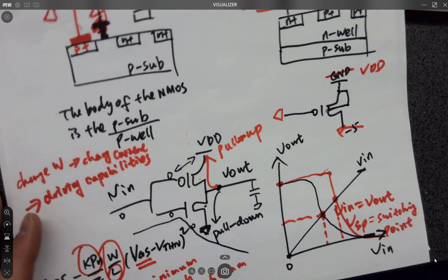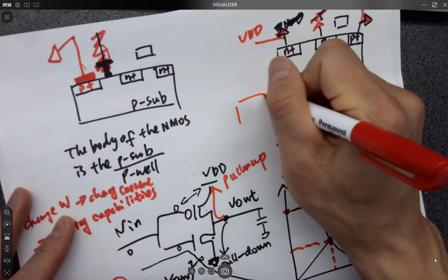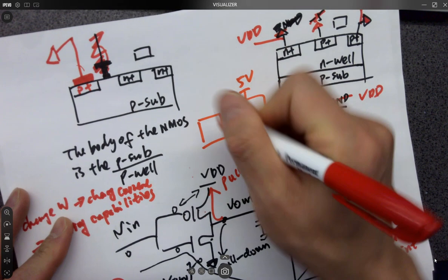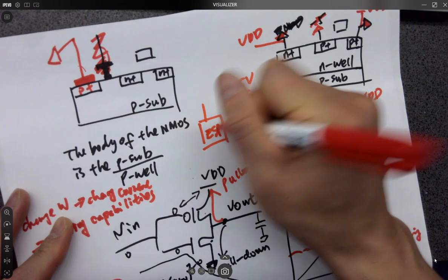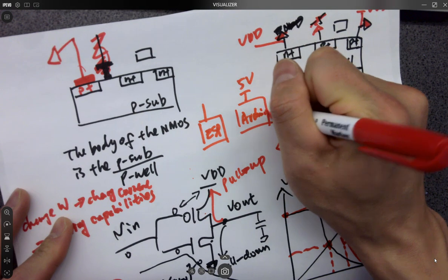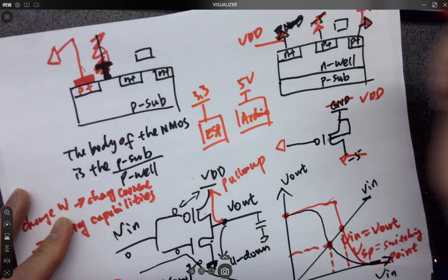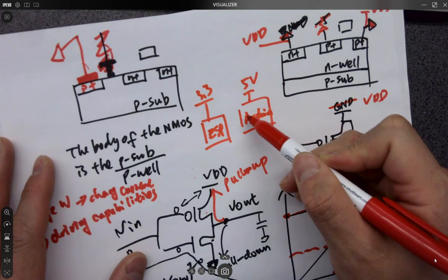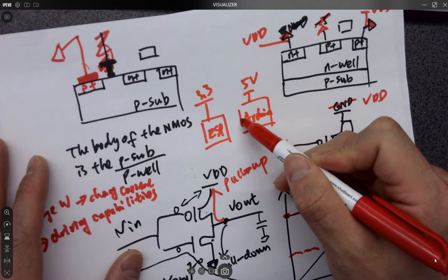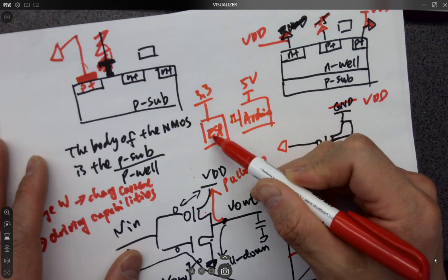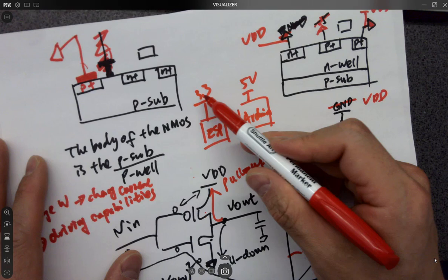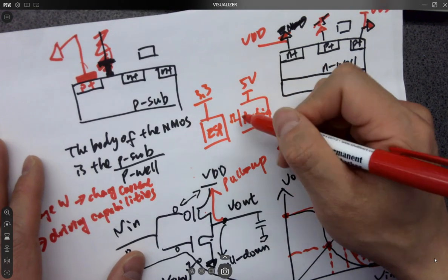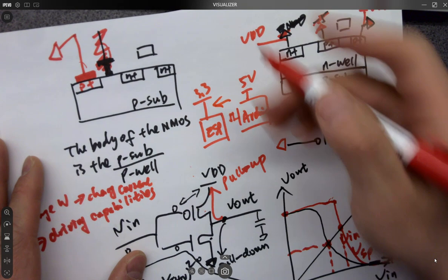So for example, you are using a 5 volts logic, like Arduinos, right? You're having an ESP, which is 3.3 volts, and you are thinking, hey, can I communicate between ESP and Arduino? Probably the Arduino's digital logic will fry this chip because this guy cannot handle anything higher than 3.3 volts. That's true. So you have to use a voltage divider for the signal from here to here.